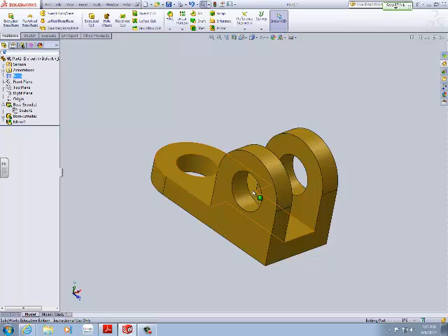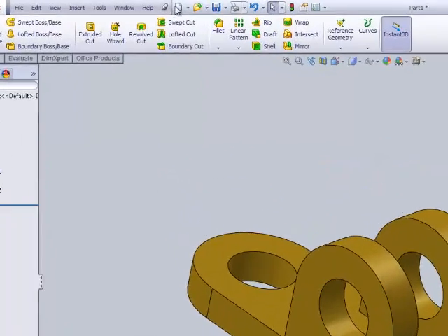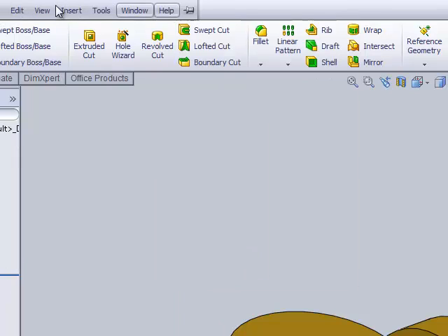Now the next step in this Lab1A is it's requesting us to check your density volume. So that's how we're going to test this out. If your drawing is correct, the volume should be correct. And to get that information, if you don't have this open up here, sometimes you have to hit that plus sign.